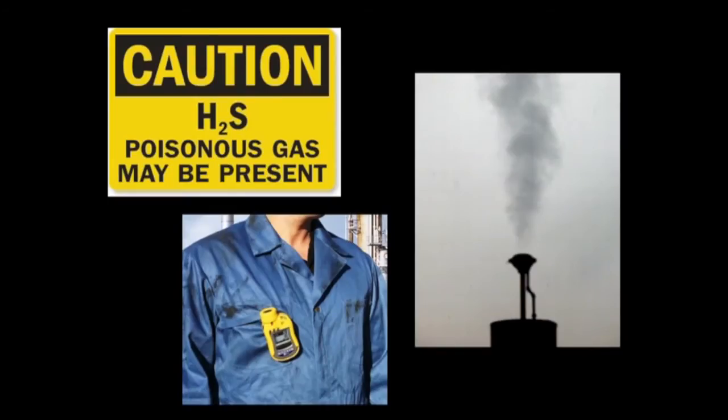H2S also smells like rotten eggs, but is much more dangerous because the smell can rapidly overpower the senses, leaving the material undetectable and tricking the person into a false sense of security. H2S paralyzes a person's breathing mechanism and can quickly result in death by asphyxiation.